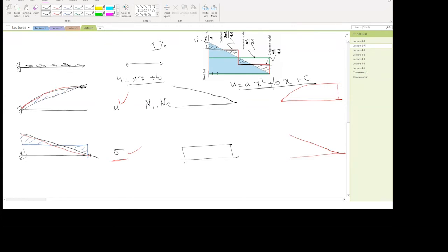Now, if we use the parabola equation, we can capture this variation exactly. And then the derivative of the parabola equation is going to be a line equation. So the derivative of this equation is going to be 2ax plus b, which is a line equation. And the line equation can capture the exact amount of the stress. So this would be a lot more efficient than using lines or many lines.